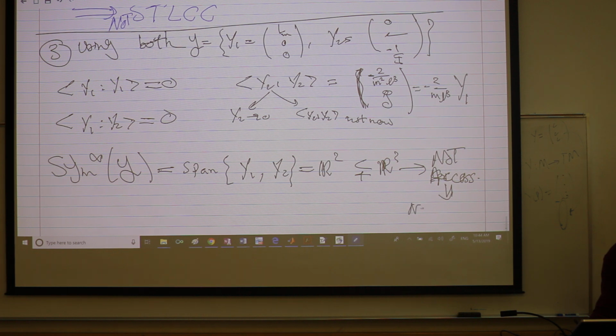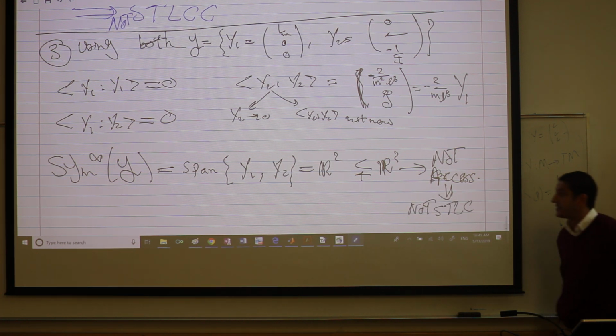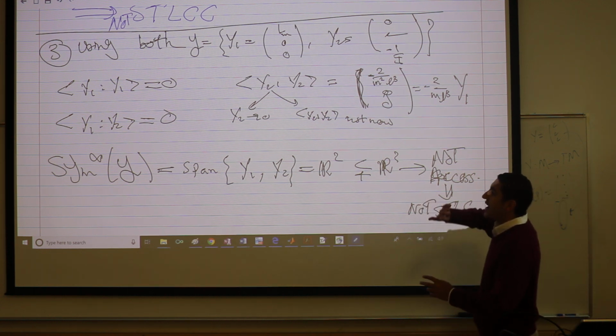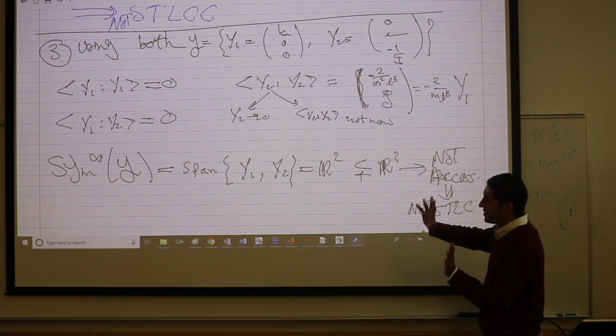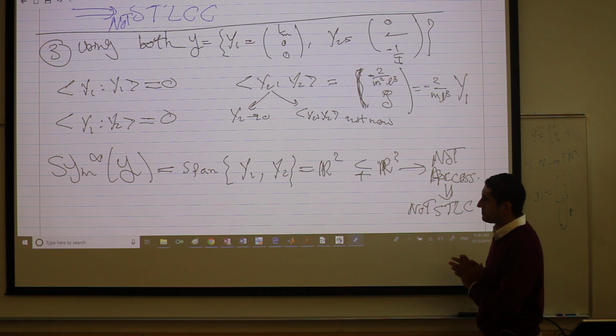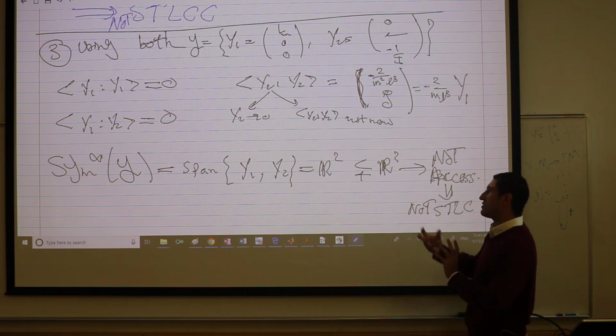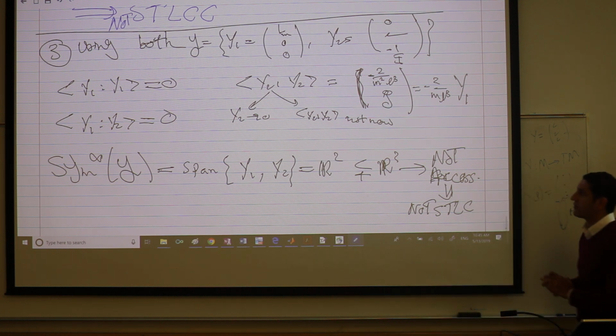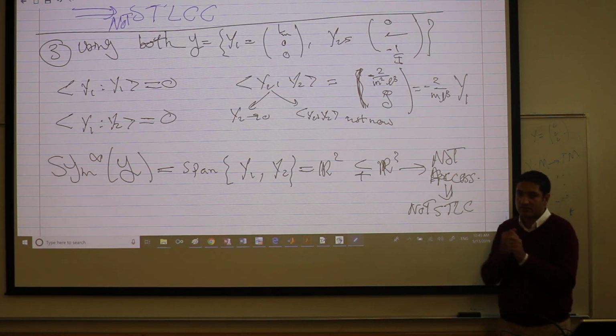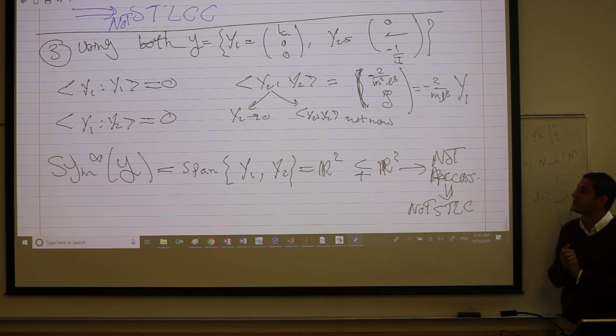And it's not small-time locally controllable in the entire state space, position and velocities. Yeah, indeed. This is why it's an underactuated system, I have 3 degrees of freedom and 2 controls. This is an underactuated system. Dealing with underactuated systems is hard, because how can you generate acceleration or force in the other missing direction? You will not be able to do it all the time.